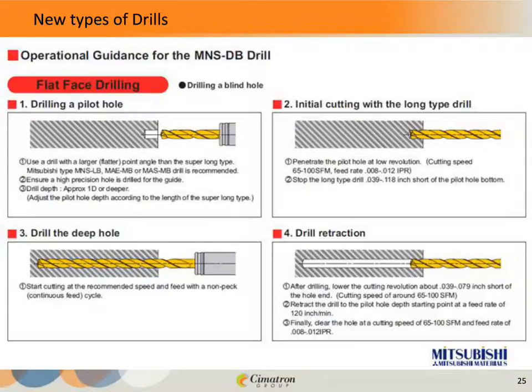Prior to breaking out, we want to slow down the feed rate, and then slow the RPM down as we come out of the hole. And then of course repeat this process. So this is going to require some unique settings for programming, because canned cycles don't really handle this type of operation.